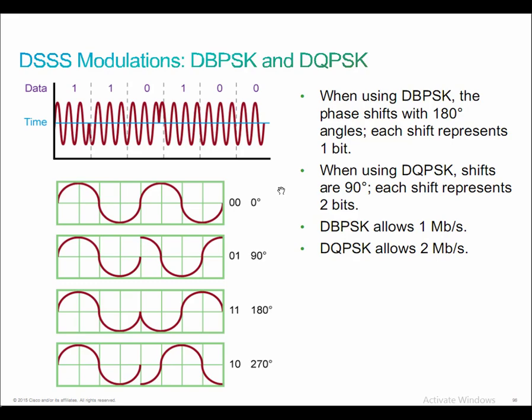When you get into OFDM and you start to get into a 54 meg standard and faster standards, they simply start representing more and more quadrants, which now allows us to represent more and more data, right? More and more different sequences of bits. There's 4 possible combinations in this particular case, 0, 0, 0, 1, 1, 0, and 1, 1. So there needs to be 4 possible alterations of the wave.